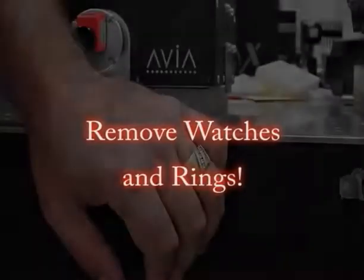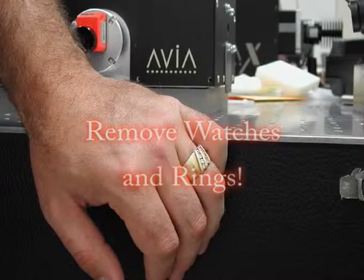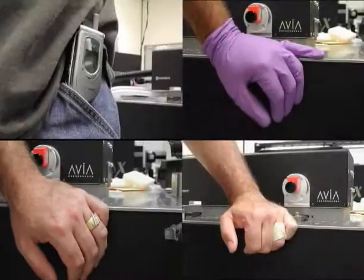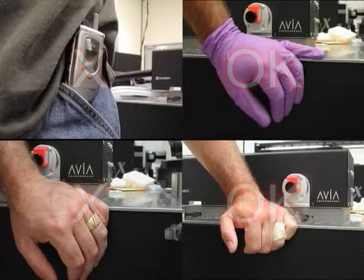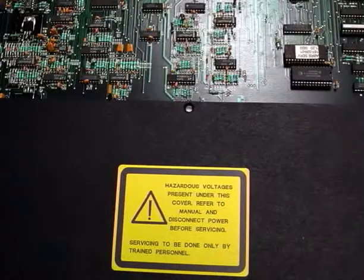Gold is one of the best laser light reflectors, and it is required that you remove or cover all rings, jewelry, watches, and any other metal accessories that you are wearing that could possibly reflect or scatter the beam. Removing these metal objects is also required when working with electrical components, as the majority of these items are conductors and can pose an electrical hazard as well.